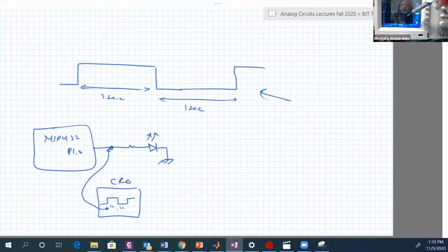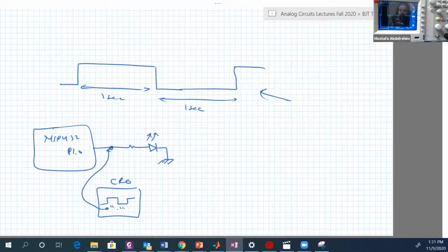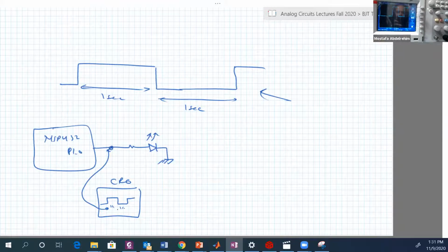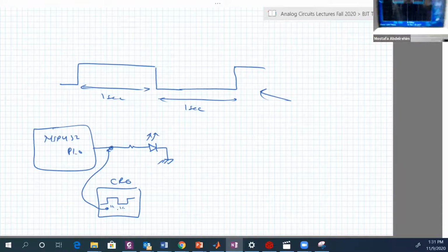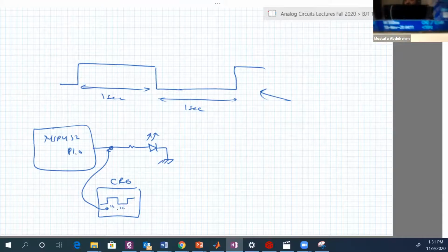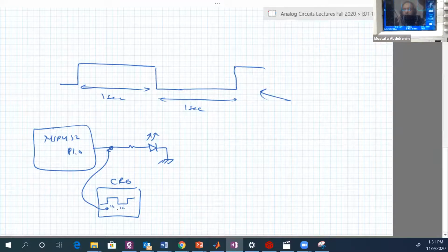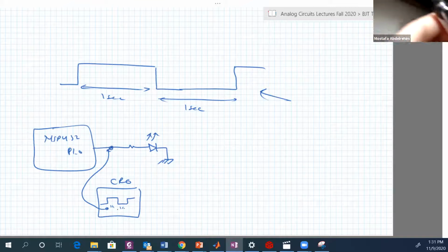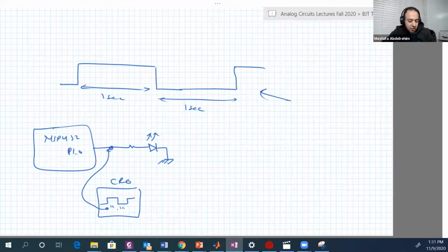Now how about the time? If you look here, the time per division is 500 milliseconds, or half a second. It's really hard to measure, but each pulse is 2 divisions. So 2 multiplied by 500 milliseconds. I'm gonna show you 500 milliseconds here. You guys can see it. Yeah, 500 milliseconds. So 500 multiplied by 2 will give you 1 second. So this is a proof that we have created a not very perfect, but some precise time delay, rather than making for loops or stuff.